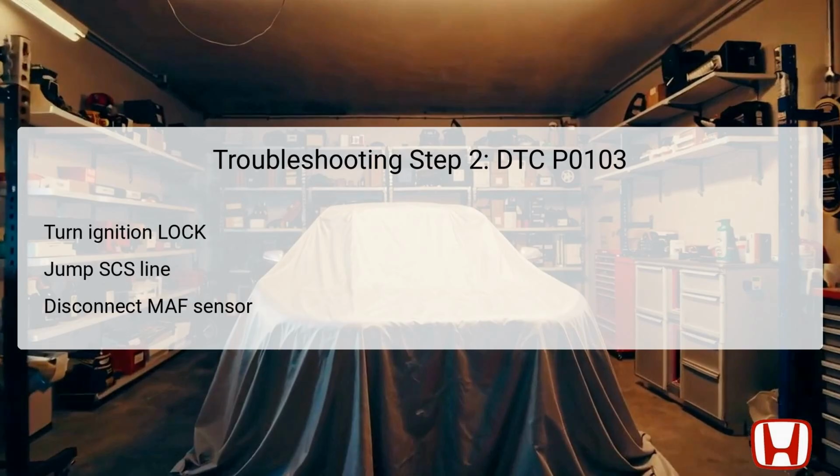Disconnecting this connector disconnects the sensors from the ECM/PCM, allowing you to inspect the wiring for potential issues. Now, proceed to disconnect ECM/PCM connector A, which has 49 pins. This step is essential for checking the continuity between the connectors without interference from the ECM/PCM.